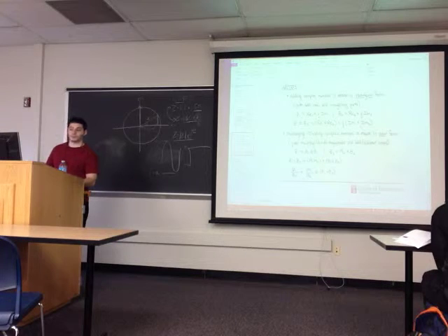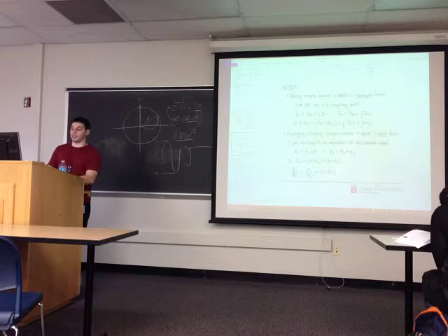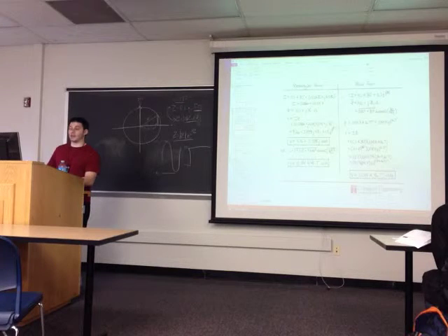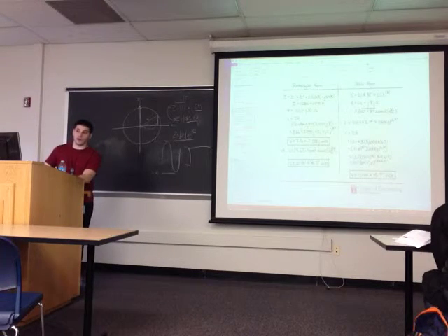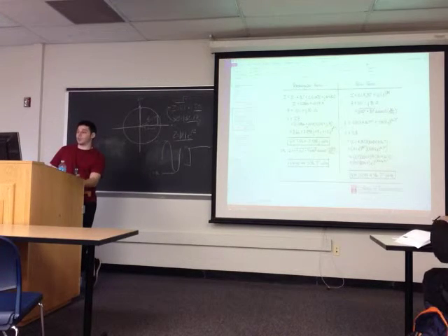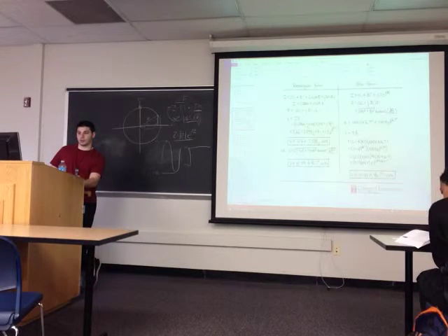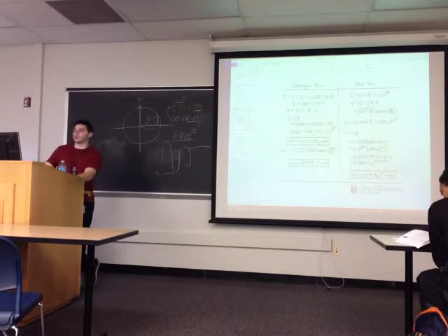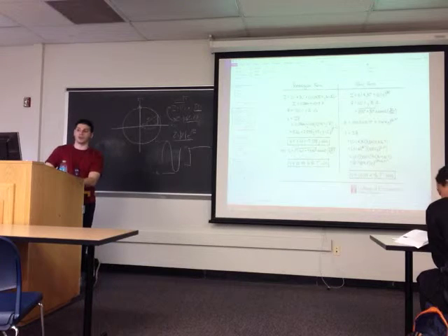So when do we have to multiply and divide complex numbers? Like the previous example, where we have a complex value I, the current, and a complex value Z, the impedance, and we multiply them via V equals I times Z to find the voltage. So we're multiplying two complex numbers. I is complex and Z is complex. But we just chose to use both ways to get the same answer. You can use both ways, but the notes are just explaining the easier way of going about it.